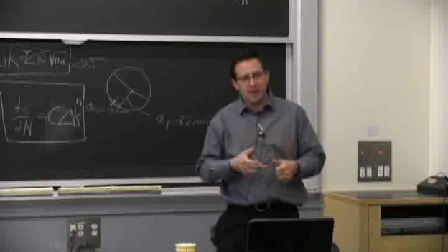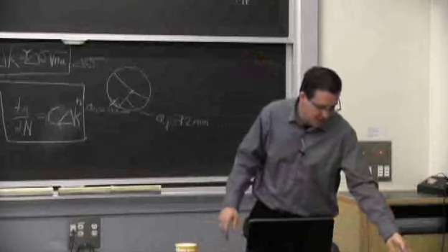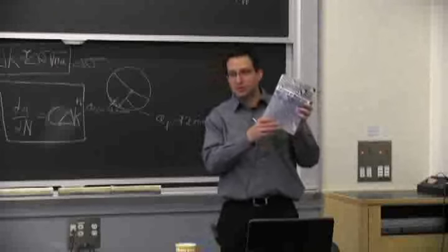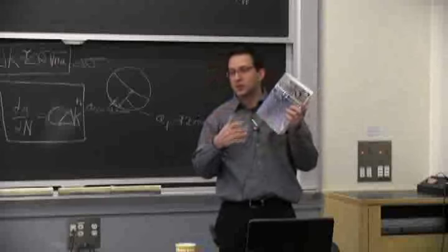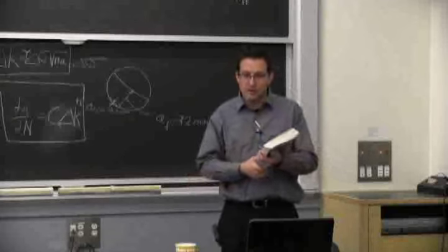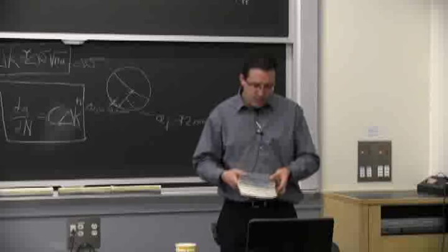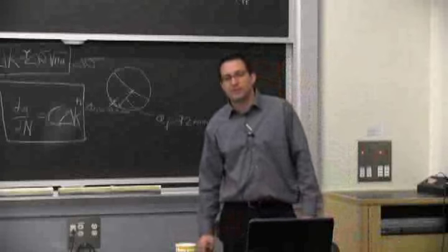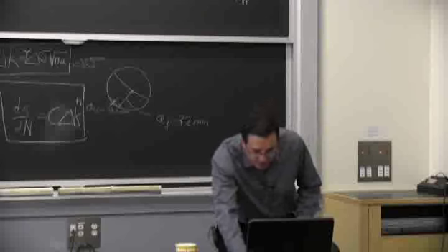So the hardening and the size of the zone affects whether you can get into this. I mean, it's good looking, but it's really bad as far as the whole industry. It means that the material weakens each time you go back and forth. So to avoid that, you want to have a bigger plastic zone if you can, and there are multiple ways to do that. Generally, it's with a lower yield strength and a higher hardening. It just goes against all the other variables.